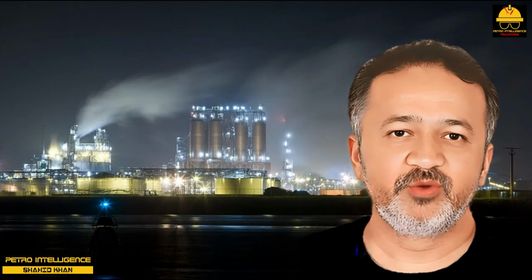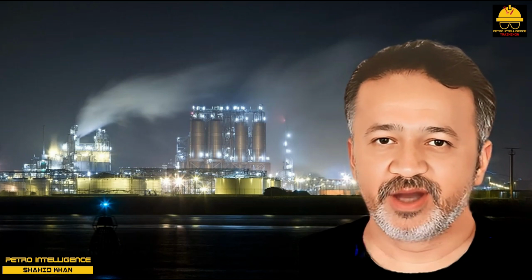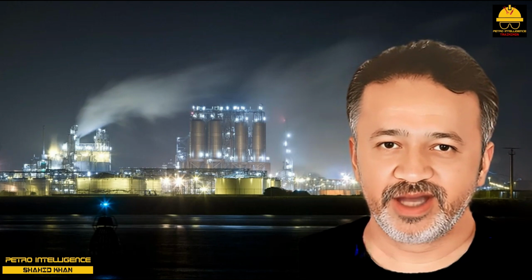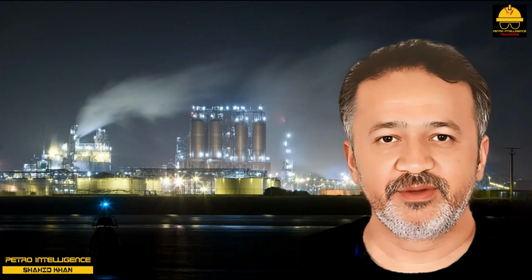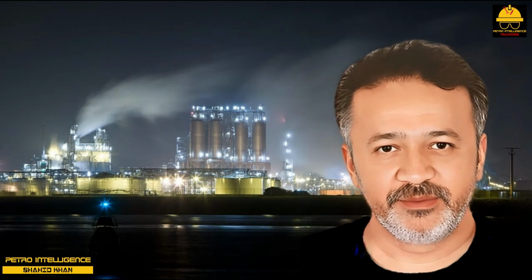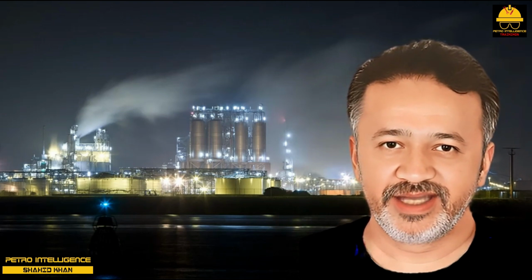Backflush connections in water coolers. I prefer to place water cooler backflush connections on the channel head cover. This is mainly because the piping design is not under my control, and thus the tube side backflush connection may be omitted by the mechanical designer. My rule of thumb is that I don't want the backflush connection to be less than half the ID of the cooling water supply line.